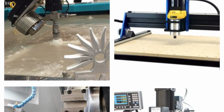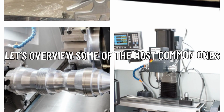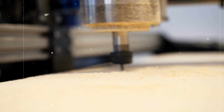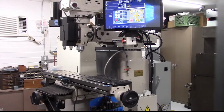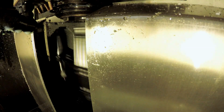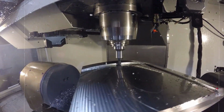There are quite a few different types of CNC machines out there. Let's overview some of the most common ones. CNC mills use a rotating cutting tool to remove material and create a part. You've got 3-axis mills that move along the X, Y, and Z axes, as well as 5-axis ones with additional rotational capabilities for more complex contours. The 5-axis machines can tilt and pivot for greater flexibility.